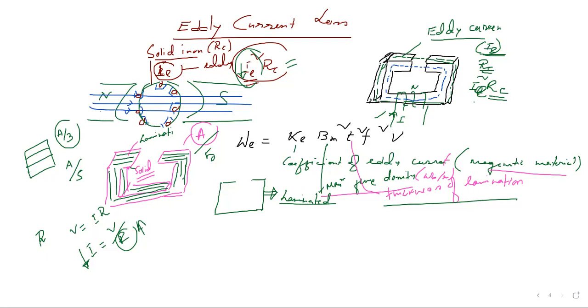But sometimes the eddy current loss is useful. Maybe in your case it is not required, but as an electrical engineer, the eddy current loss is sometimes used for some other purpose. Are you familiar with the term induction heating? In induction heating, the eddy current principle is used. And when we discuss some measurement circuits, one of the torques, the damping torque, is also provided by this eddy current loss.